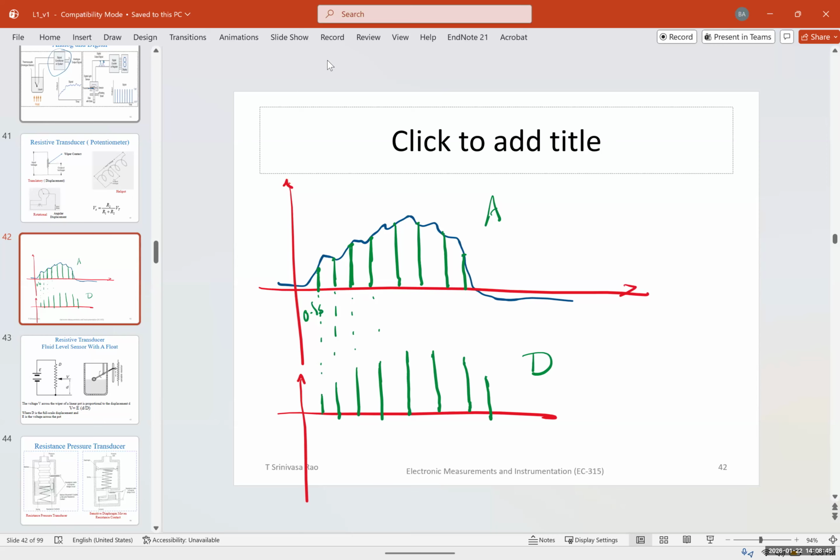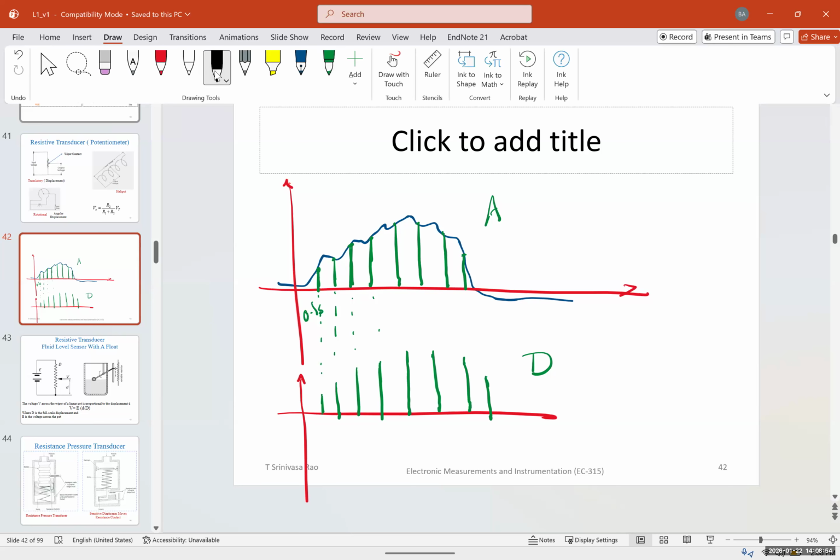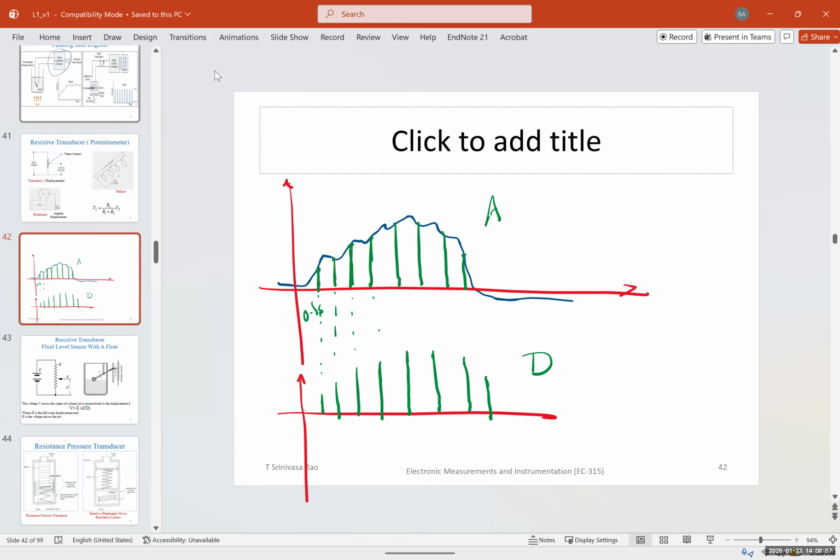Now, if I want to convert this back to analog, for example, if I want to play it on a speaker, and the original was an analog signal, the only thing that I need to do, how can I do it? I could simply connect these signals to each other, okay? So connecting them using what we call an envelope detector. Now, how can I take the sampling with a simple switch? Imagine I have a switch connected to the upper one, and I can control when to open and close the switch. That's going to be my sampling rate.